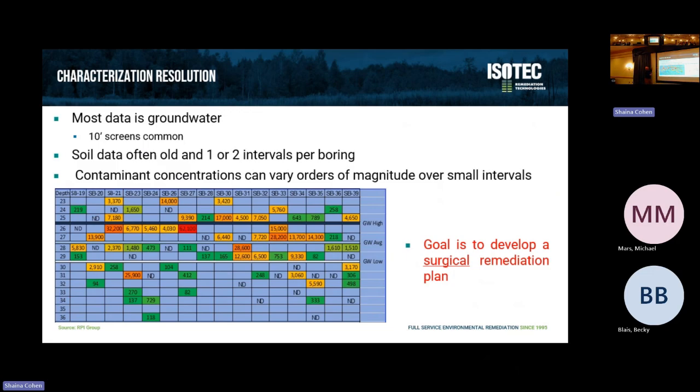That's a significant drop off. And if our monitoring wells are 5 feet or even 10 feet, and if the geology is different across that 10-foot layer, what's coming into that well may be highly impacted by the much less impacted zone, and we don't have a sense of how high this is. And we even see on some of these that, if you had a 10-foot screen here, we may think we have to treat that, but all of the contamination in a lot of these locations is only maybe 2 or 3 feet thick.